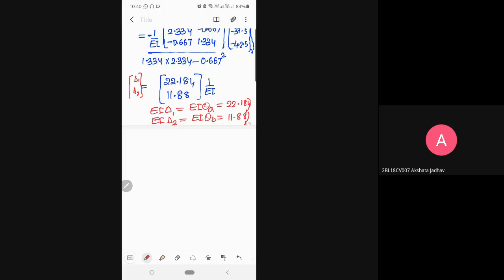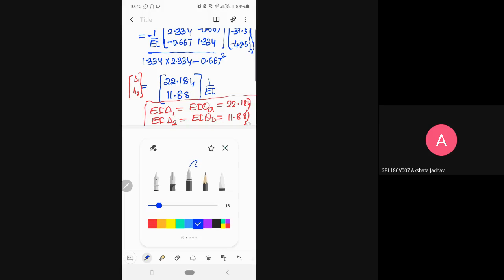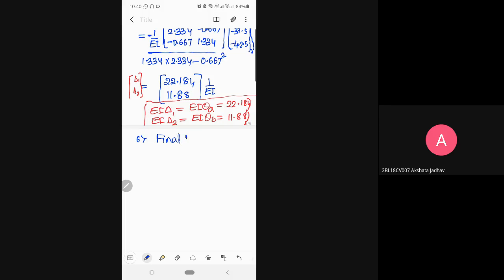So this is the same as in the slope deflection method. You determined the unknown displacement, right? So these are the unknown displacements. The same displacements you get here. You can take the same problem of the slope deflection method and solve it. You'll have the same unknown values here. Clear? Now with this displacement, our aim is to determine the moments, right? Forces. So by determining the displacement, now you can determine the forces. The last step is the final forces, final moments.